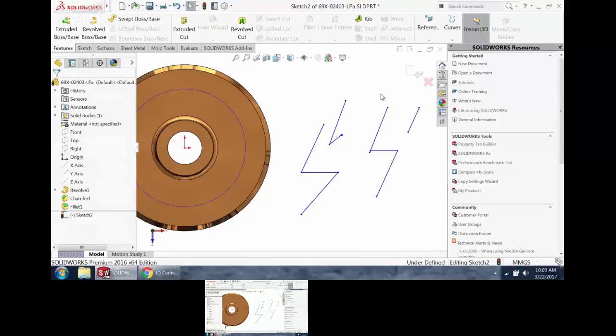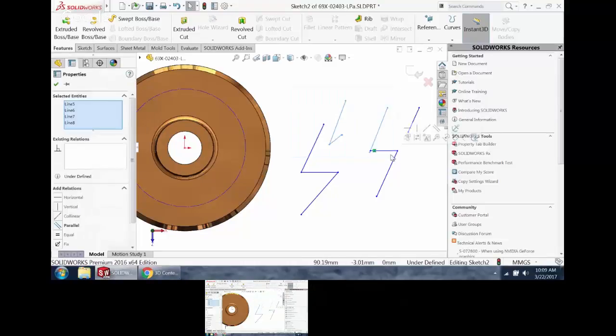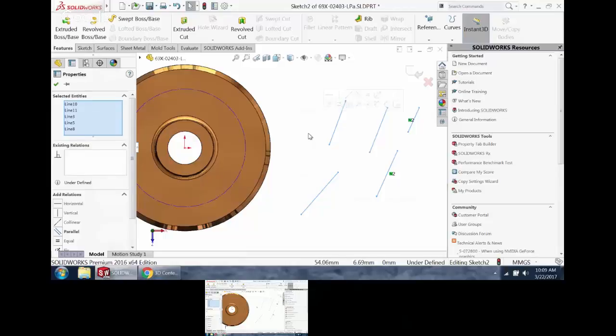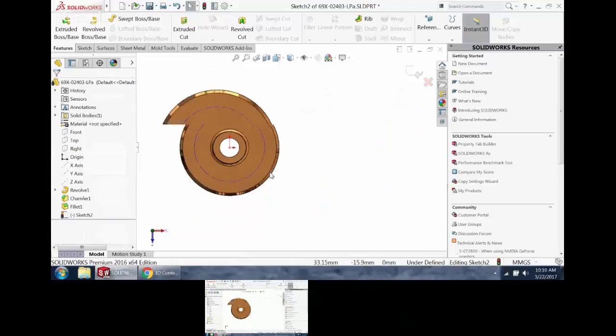As we're talking about how to select stuff in sketches, if you do a box select from the left to the right, you'll see that the box is blue. When that's happening, only things that were entirely in the blue are selected. If you go from right to left, oops, I'm holding my right mouse button. So on my left, here we go, right to left, you'll see it turns green. Green means anything that touches that box will be selected. Hit the delete key and away it goes.